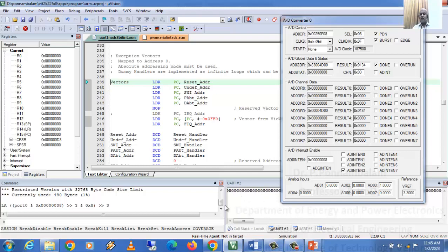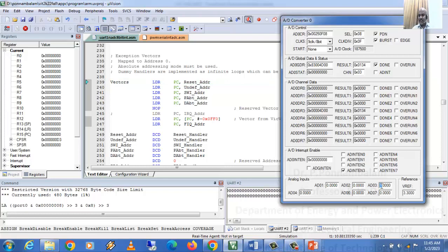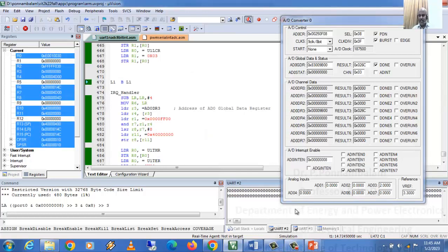The UART window, the serial window, always gives you the value in terms of ASCII. So it takes in ASCII and displays it as a character. So whatever changes you do will get transformed into some kind of alphabet. So that alphabetical character change is happening, you can see.